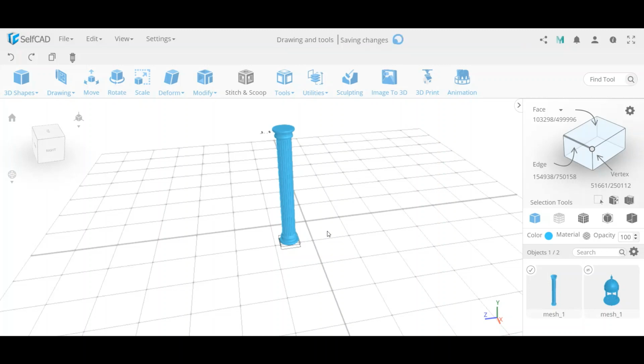So what's happening is, if you have something that's called a shader for backface culling, that means it hides everything that's not facing outwards because you cannot see them. And similarly, from a rendering perspective, there are a lot of algorithms, a lot of tools, that operate based on the direction of the faces, based on the normals. And if something is inverted, flipped, the tool may not work as expected.